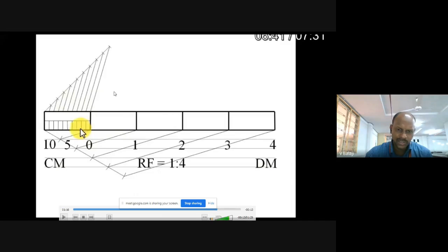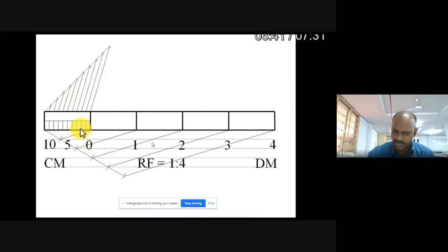In between these two extension lines, you draw one horizontal line, keeping a distance of 1 centimeter from the basic rectangle. Don't disturb this rectangle; this is the constructed scale. Away from that scale, you take a 1 centimeter gap, draw one horizontal line between the two extension lines, and on it you write freehand 3 decimeter, 7 centimeter. In this way, you can answer any problem. Understood?